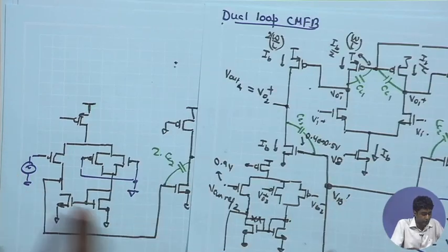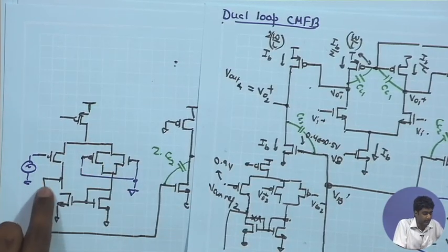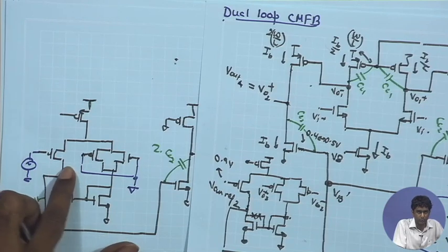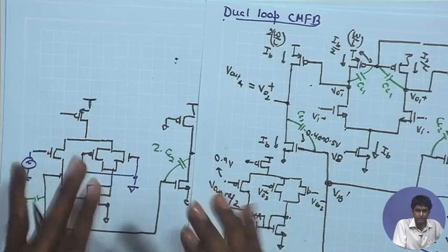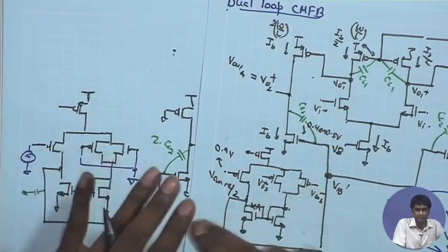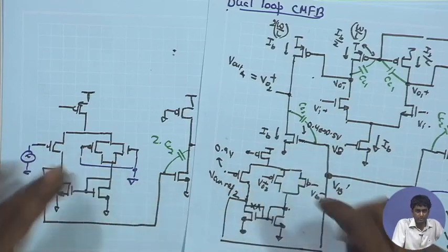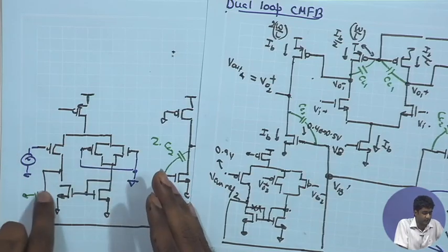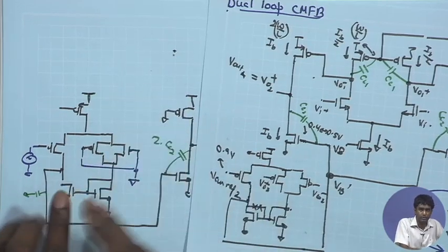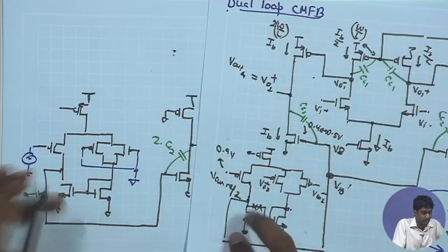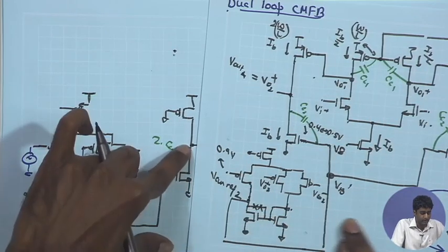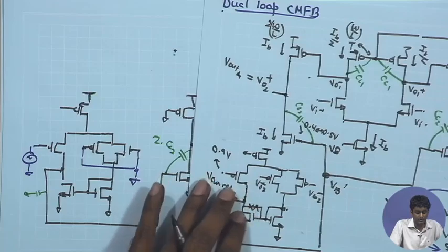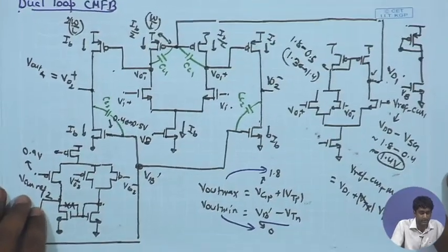And as a result, once again it is going to compensate the pole of the error amplifier. It is going to result in a large Miller capacitance at this point, which is going to push the pole over here at this high impedance node towards low frequency. So, the overall compensation scheme is the same as what we have discussed for the differential amplifier based on Miller compensation, where the lower pole is pushed towards lower frequency because of this large Miller multiplication, and the second pole is pushed towards higher frequency because of the effective impedance of the second stage dropping at high frequency because of this CC. So, that is what happens, and we have seen what is the effect of that in overall compensation and stability.